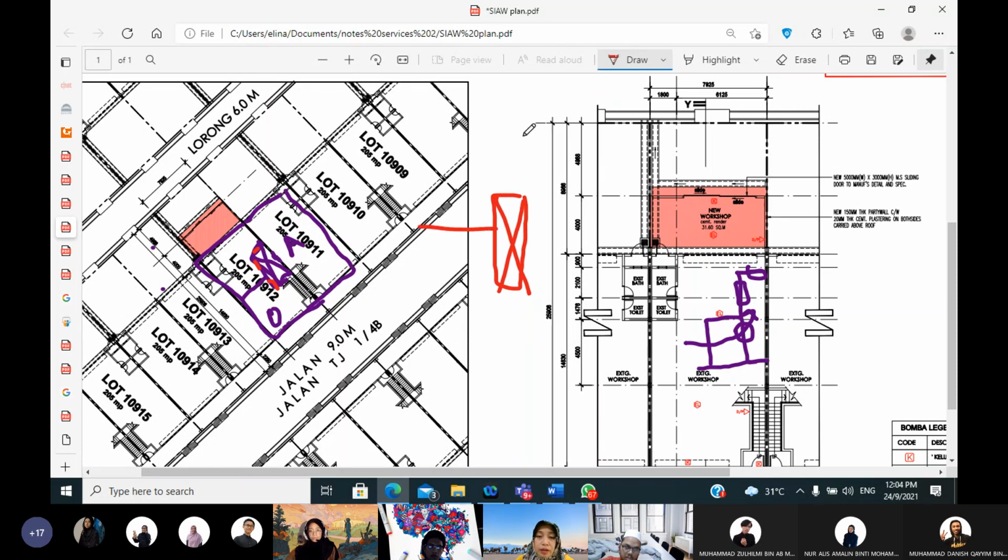So this is a room in the middle. There's no light, there's no ventilation. So you can propose there would be a window here. So this room is ventilated through the light well for lighting and for ventilation. That's the purpose of light well.